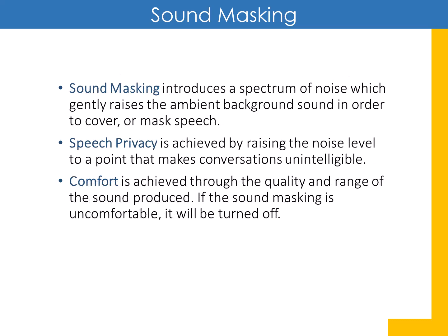Sound masking introduces a spectrum of noise which gently raises the ambient background sound in order to cover or mask speech. Speech privacy is achieved by raising the noise level to a point that makes conversations unintelligible. Comfort is achieved through the quality and range of the sound produced. If the sound masking is uncomfortable, it will be turned off.